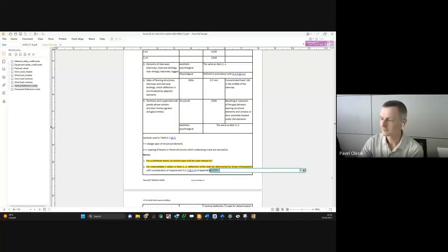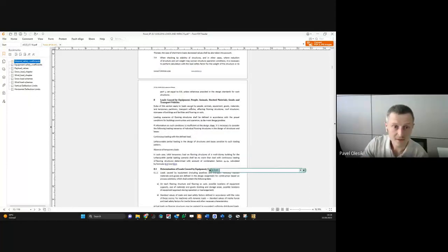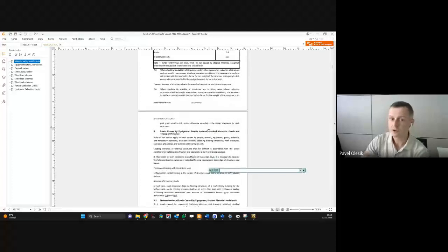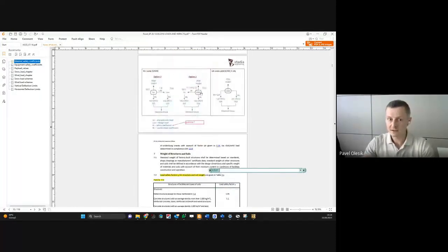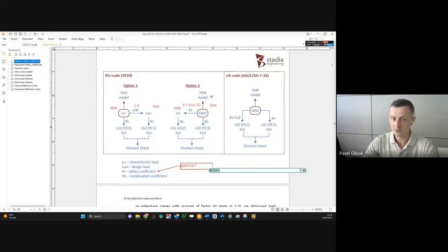We are decreasing load with this duration factor. Yes, we can use different coefficients. For example, if you are working with design values, and you are calculating SLS with some coefficient, and your KF ratio is 0.72. In this case, we can multiply it by 50% and put 0.36 for this coefficient.